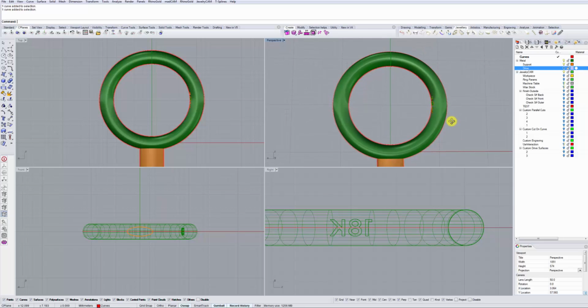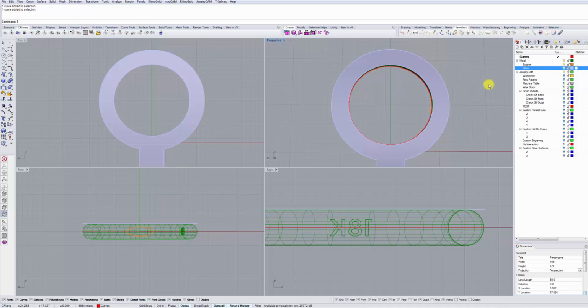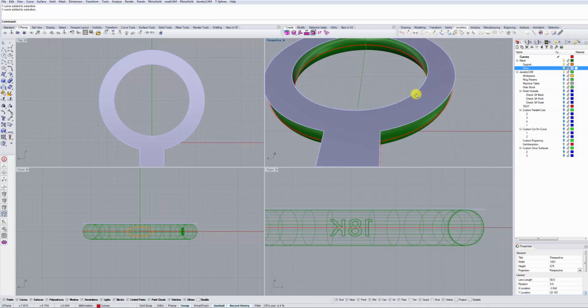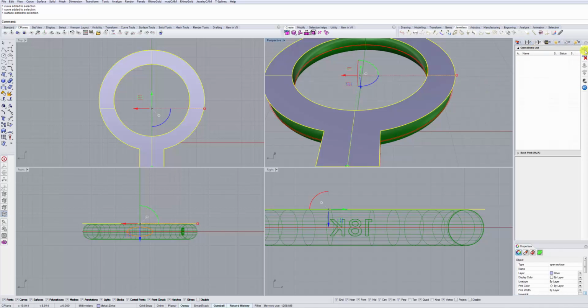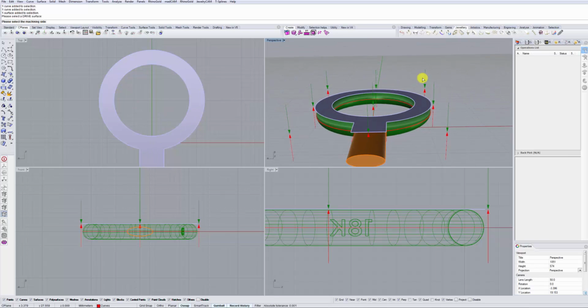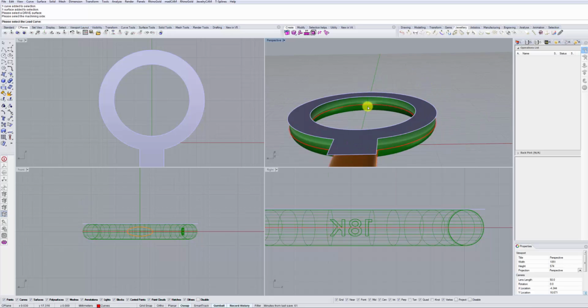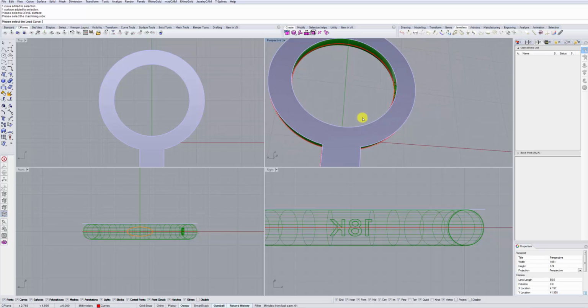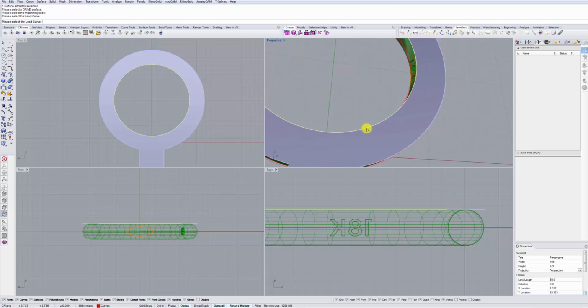So let's begin with very simple 2D flat drive surfaces. So here's one, for example, that I've added. It's basically a silhouette of those two boundary curves made into a planar surface. So let's click Add New Custom Operation, specify Drive Surface, select this drive surface. You'll see it will ask us for direction of approach. We'll use this direction. Lead curve, we'll use the boundary edge for the lead curve, which will mean that it will cut things this way. And for boundary curves, we'll leave that be. We'll just use the drive surface itself.